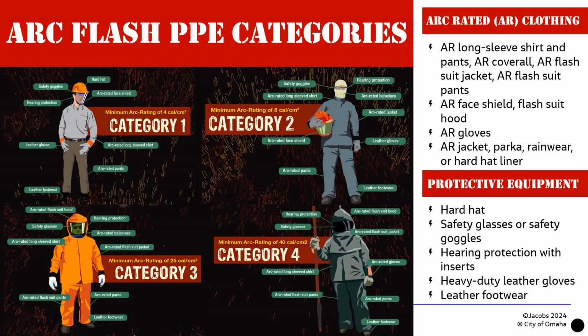For more traditional workers, wearing the correct PPE as per the incident energy levels enables protection, which includes both clothing and protective equipment. The arc-resistant clothing protects workers from burns and provides a solid line of defense, and this provides a level of protection more advanced than the regular protective equipment.